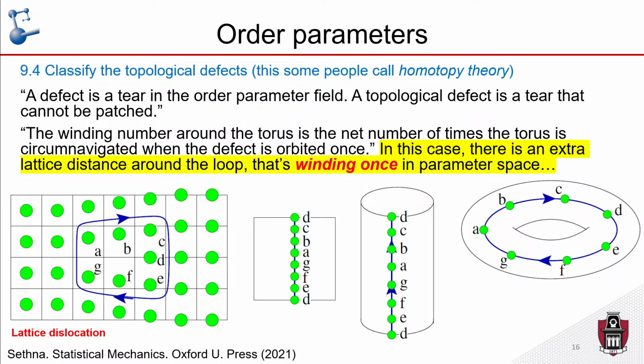You want to notice that you can have dislocations that are horizontal or dislocations that are vertical, and we're going to come back to this in a moment. But the idea is that in regions away from this special part of the crystal, if you take this loop, you are going to enclose 8 atoms. So basically, you enclose 9 atoms, but you have 8 atoms that are closest to this loop.